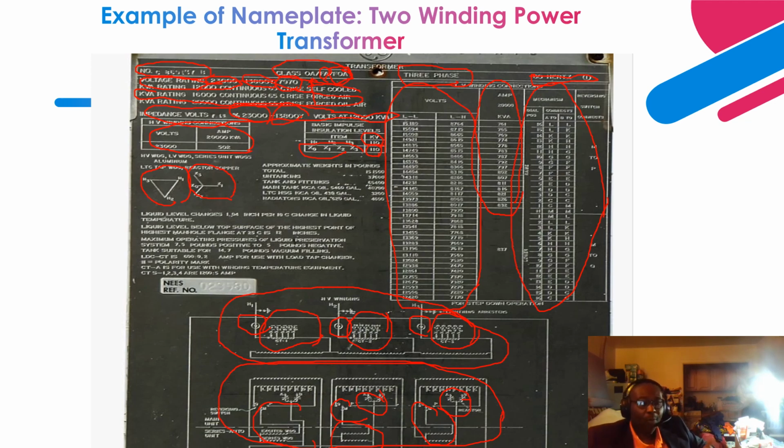So for this amount of temperature change, this is the liquid level that changes in the transformer. It's a variation of liquid level in proportion with temperature, from the ambient 25 degrees Celsius, that room temperature that is used to fill the transformer under vacuum.